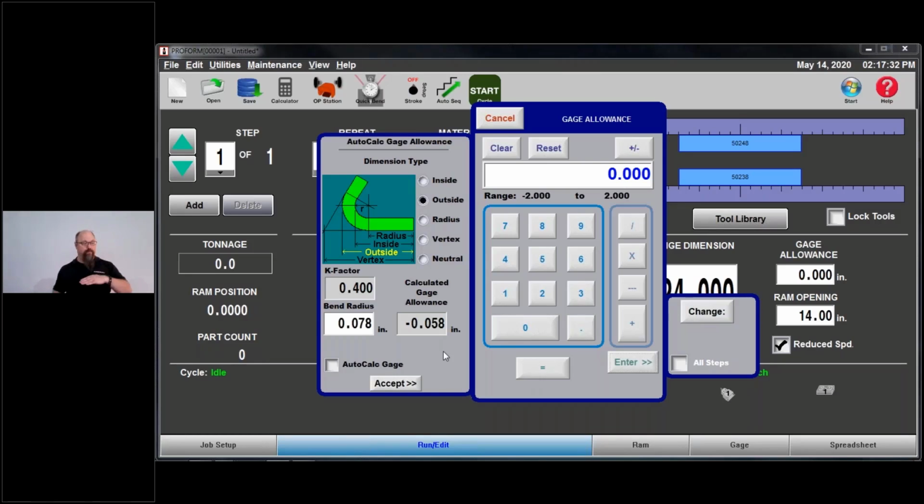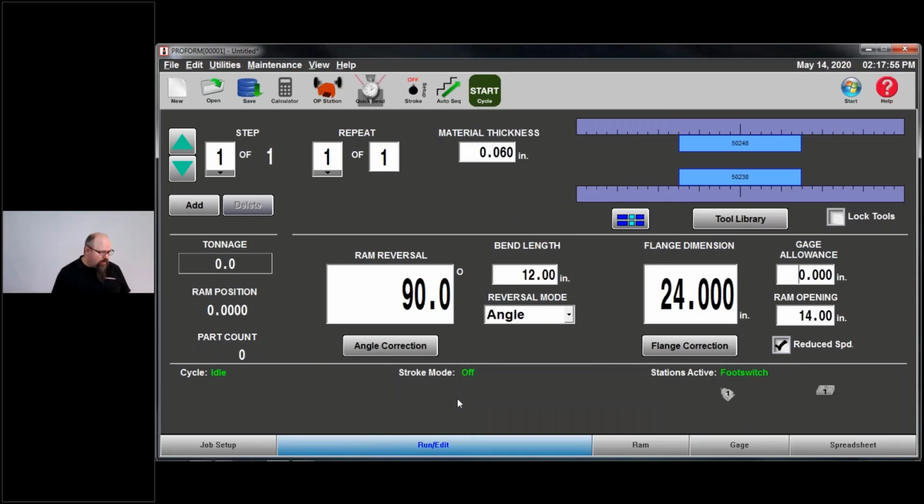2.942. And then when I bend it, it'll stretch out to 3 inches and give me plus or minus 3 or 4 thou, depending on the alignment of your gauge. I should be less than 5. I will say that. So if you're doing steel, this thing is a wonderful thing. If you're doing other materials, I can't really speak to that. Yeah, shrinkage, bend, plastic. Yeah, that's right.